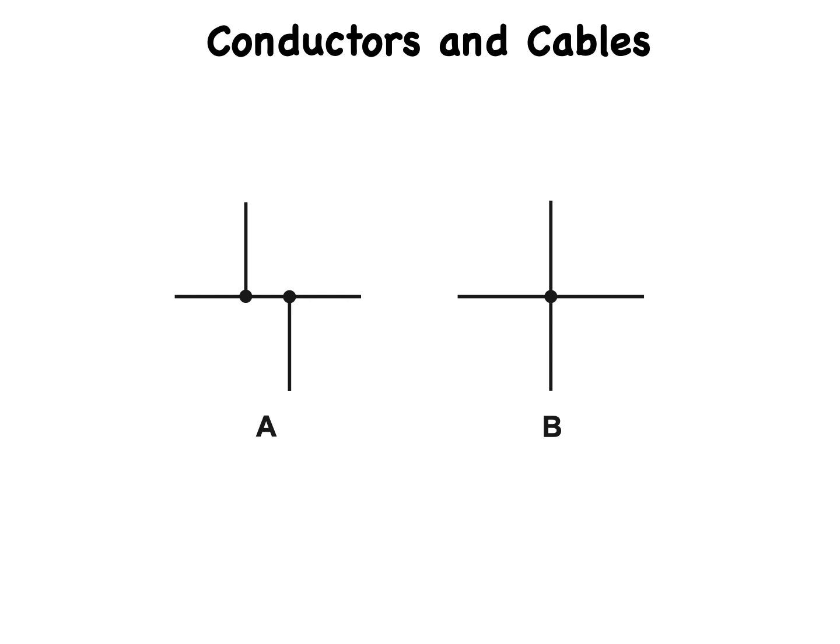Just as a reader might miss a black dot at a crossing point, as in Figure B, another reader might see the wires crossing in the previous slide and imagine a black dot when it isn't there. Then the reader will think the 2 wires connect when in fact they do not. This problem rarely occurs in well-engineered schematics where the draftsperson makes sure to use big black dots and good quality printing presses. However, in some older schematics you will see non-connecting, crossed wires shown like this.